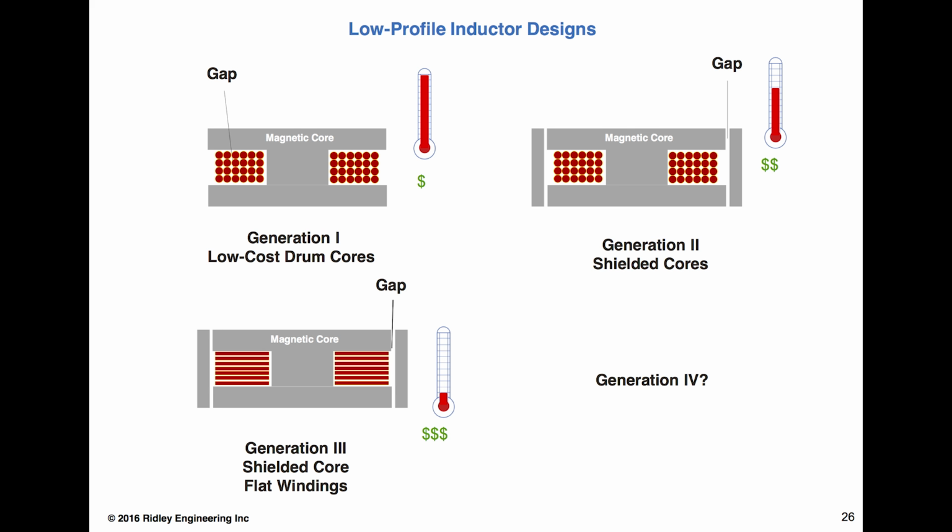But the frequency will greatly depend upon how much ripple current you've got. You can use a generation 1 at a megahertz if you've got pure DC. If it's a second stage filter and there's only DC going through it, that's fine. You can make the magnetic material out of anything you like, and core loss will not be a problem. Winding loss won't be a problem because there's no AC excitation. So you can't really answer the question without knowing the exact power level, the converter, and the AC and DC component.